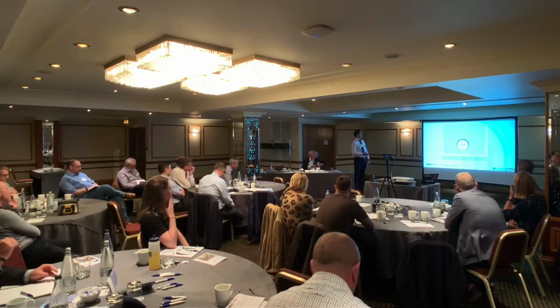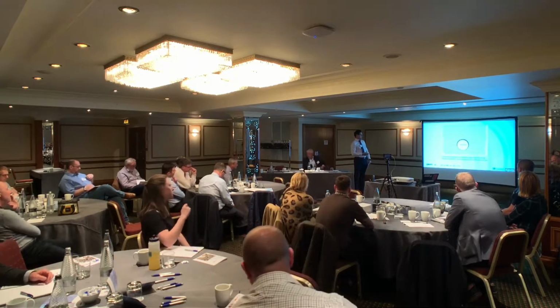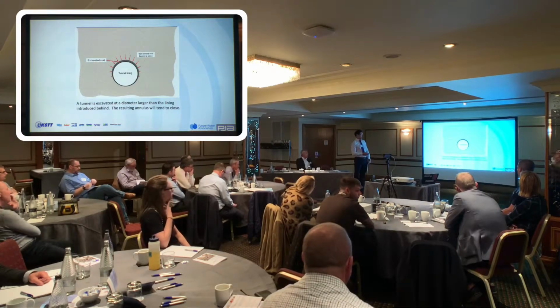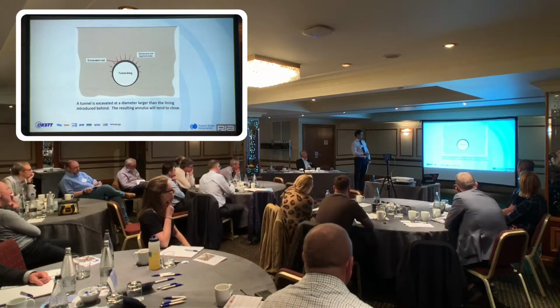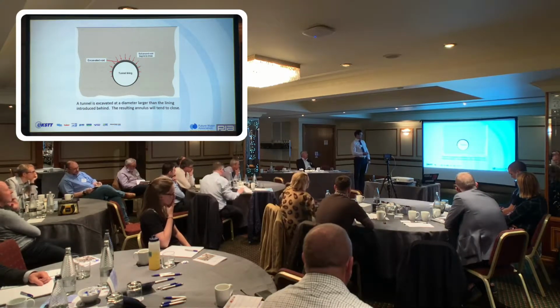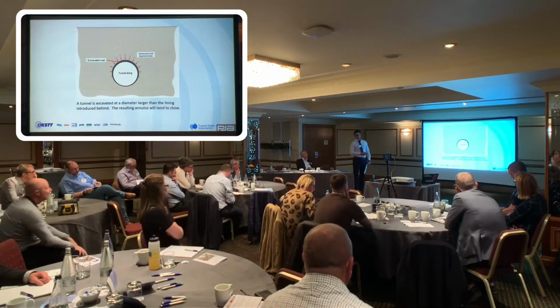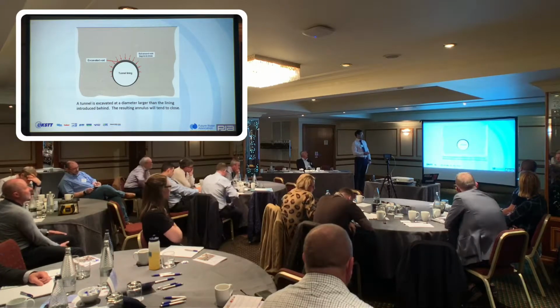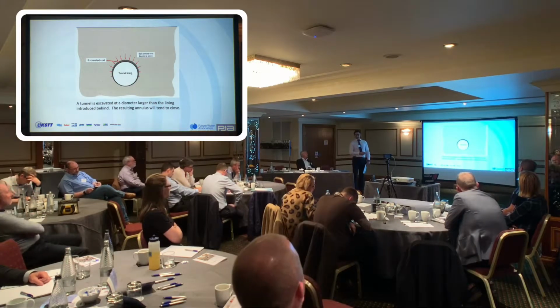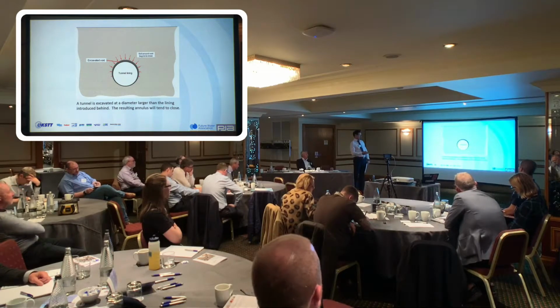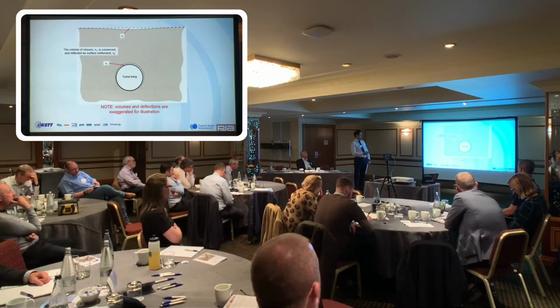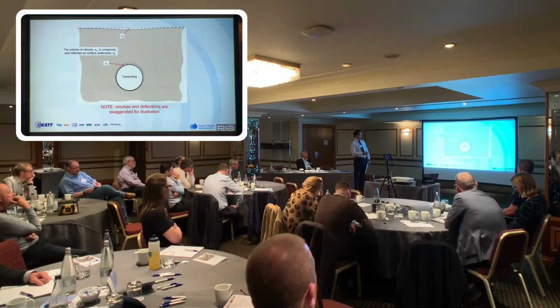As the tunnel is excavated, obviously the diameter is larger, and the lining is going to follow, so you will have a void generated, called the annulus. The soil, regardless of what it is, will generally close around that lining. How long that takes is dependent on what kind of ground conditions you have. That subsequent movement, that volume of closure, is reflected on the surface. That varies again with ground conditions and how close you are to the surface.